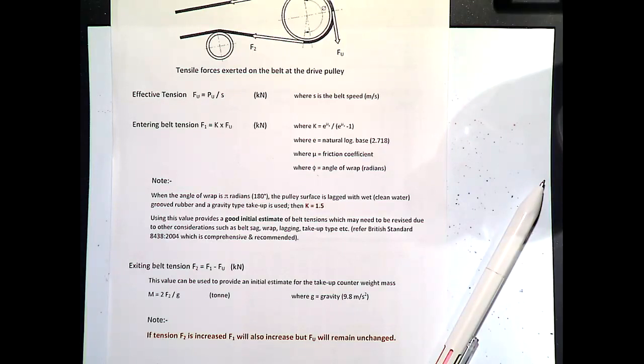All they've done is put a little bit more in the counterweight. So the counterweight here has come up now to 25. They put a little bit more mass in here, which is unnecessary. If they were having trouble with lots of belt splice failures or something, they could take a little bit of mass out. But there was no problem with that.